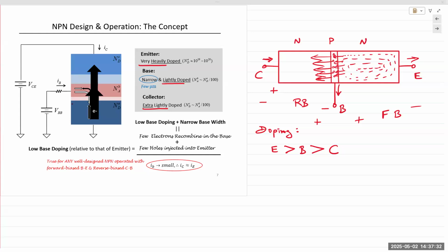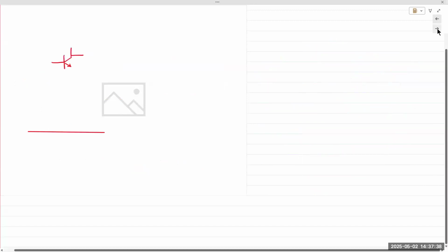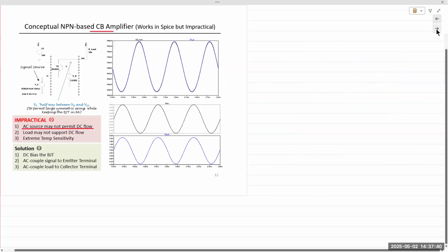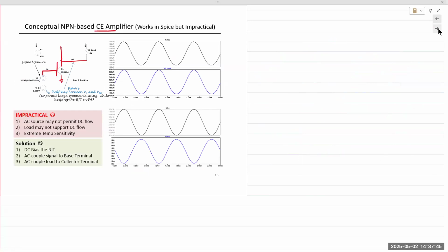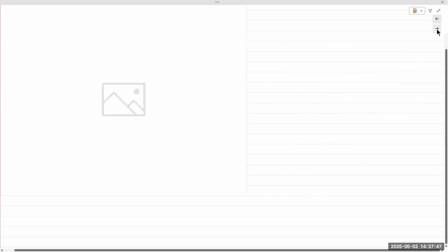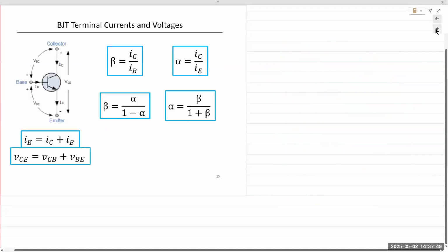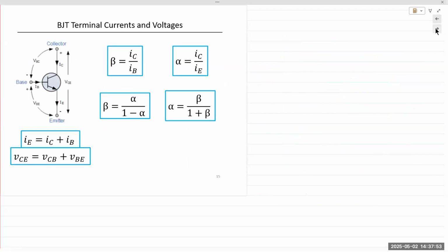All right. Recap, good? Okay, so then we looked at applications of the transistor. One of the most common applications of a BJT is using it as an analog amplifier, in active mode. And we saw the CE and CC mode amplifiers in the lab. So now let's look at some of the fundamentals. We have the BJT terminals: collector, base, and emitter.